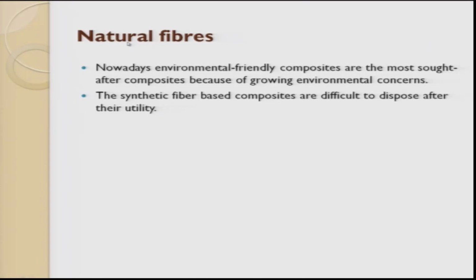So natural fibers, we saw the properties. Today people have started extracting natural fibers from banana, coir, coconut coir and so on for sustainable products. People are looking for solutions, and for the polymer used in natural fiber composites they are also trying to use recyclable ones, basically thermoplastic natural fiber reinforced composites. However, since they have a lot of processing difficulty, even today people use epoxy or polyester and use natural fiber for reinforcing. These natural fiber reinforced composites are not looked at for primary strength applications.